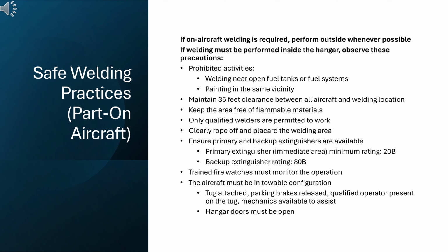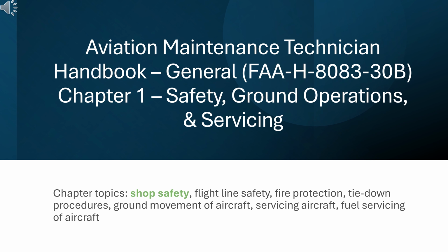During welding, trained fire watches must be in position and the aircraft must be in towable configuration. Towable configuration, for our purposes, means a tug is attached and manned by a qualified operator, the aircraft parking brakes are released, and mechanics are available to assist. The hangar doors must also be open.